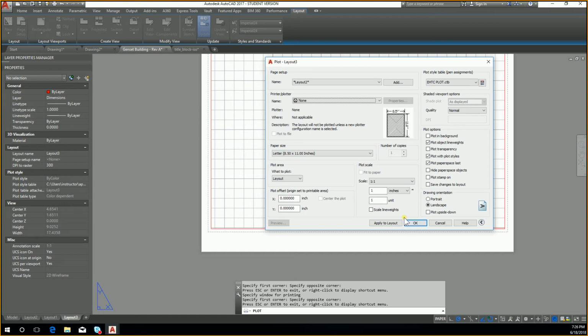Any questions about the print window? This all seems fairly simple, and right now it's hard to see the things that can go wrong, but be very careful with your setting selections. It may all seem quite easy, but the very first time you print your drawing with the wrong scale onto very large paper, and if it is perhaps a 100-page package, that's when you may not feel so great about yourself.